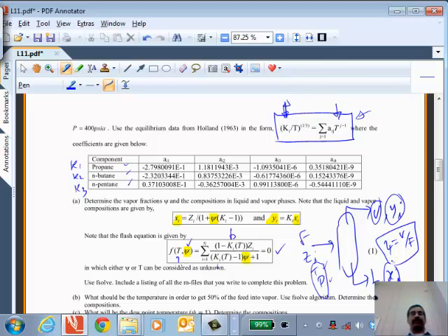So in this particular case, you have propane, N-butane, N-pentane. Propane is the most volatile material. It has the lowest boiling point. So if I start with these three mixtures in a tank as a liquid and I start adding heat, gradually increasing the temperature, I will reach a point when propane will begin to vaporize because it has the lowest boiling point. And as I continue to increase the temperature, then butane will start to evaporate, and then pentane will start to evaporate. If I keep on adding heat, increasing the temperature above the boiling point of pentane, all of them will go to vapor. So try to understand the process.